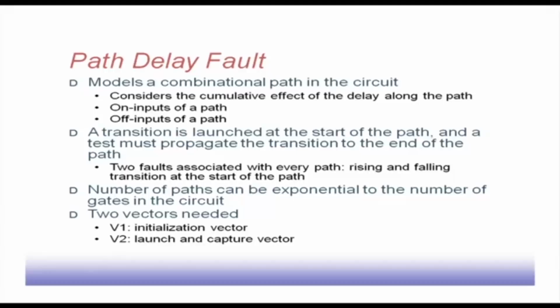So, there can be two types of faults associated with every path. One is called a rising transition, another is called a falling transition. So, these are the two types of delays that can occur. Rising delay and falling delay are normally not the same for any logic gate, so they are to be taken separately.